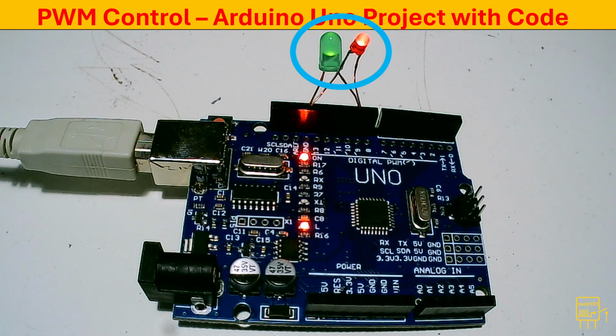I compiled and downloaded the source code to the Arduino Uno and recorded the test run execution. You may notice that the LED pair brightness is not fixed. It is changing according to the programmed parameters. It starts from 0 brightness or 0% duty cycle all the way to maximum or 100% duty cycle in 10 seconds with increments of 10% every second. The cycle continues forever.